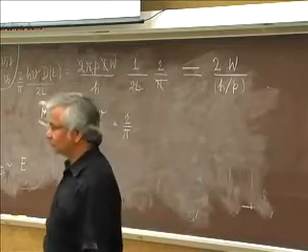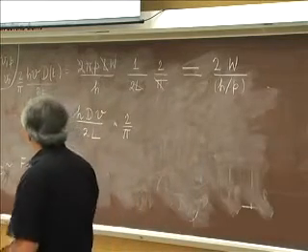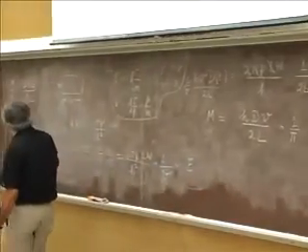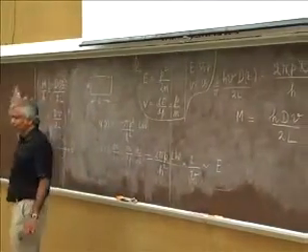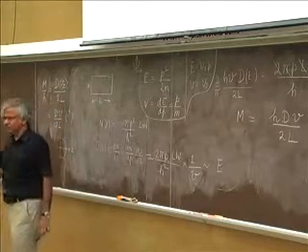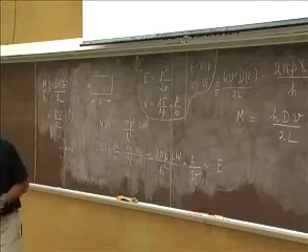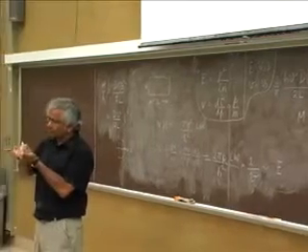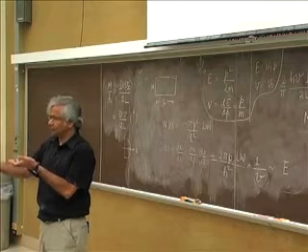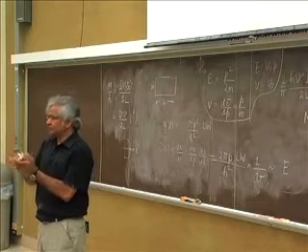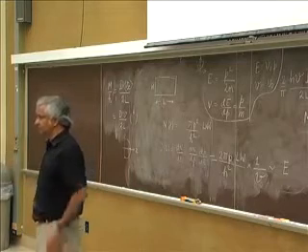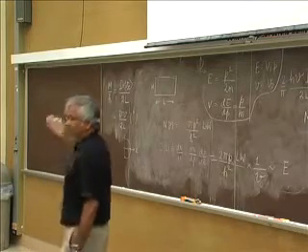That's it. You see? So this is the point that we're trying to make, that although this definition of M doesn't look like you're fitting wavelengths into anything as it stands, it's like density of states times velocity, which makes a lot of sense. Density of states tells you how many electrons you can put there. To carry current, of course, they need to be moving. They need to have a velocity. So it's not enough to have states. So that's why current depends on modes, and modes depends on density of states times velocity. That makes good sense. But yes.